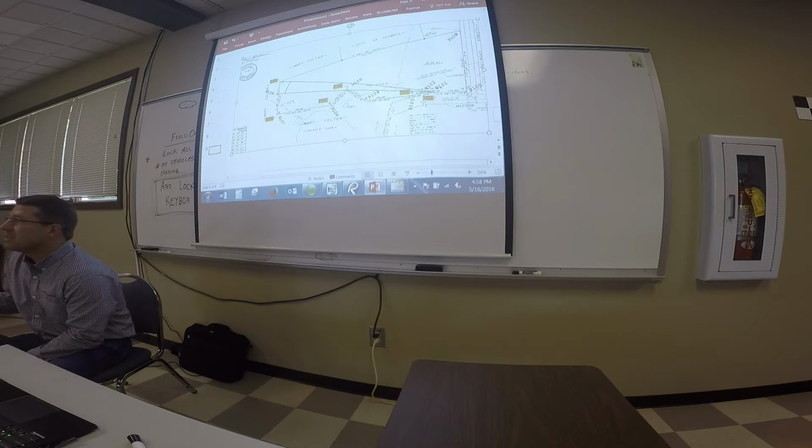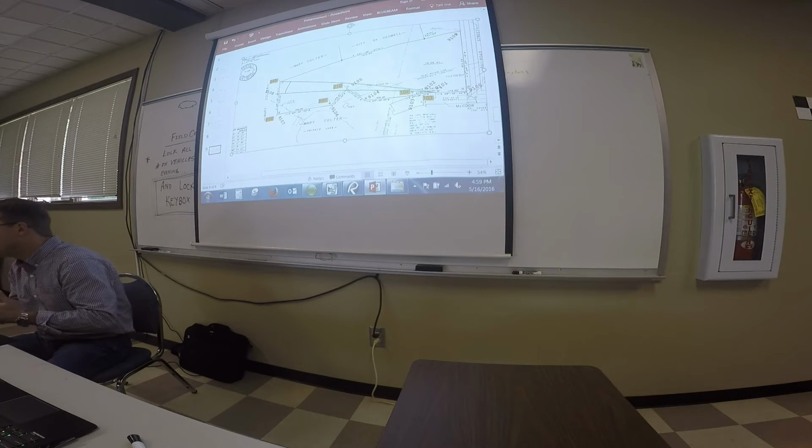Signs, for instance, if you guys shoot signs, that will draw line work. So if you put a number on it or you don't put a number on it, it will draw line work regardless. If you use SN and no number, every SN that you shoot on that site is going to get a line connected to it. That is set up purposely in our field to finish to allow us to see every place you shoot a sign on your site. We make the decision to show signs or not show signs.